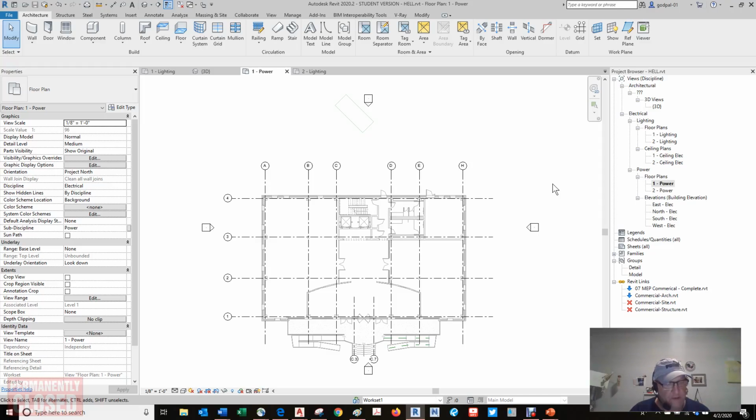At the far right end, you will see a filter icon next to a number. When you select objects in a view window, the number of selected objects will be displayed here. Click the filter icon to open the filter dialog box and refine the selection set. The 5 icons next to the filter icon determine which objects in your model are eligible for selection.